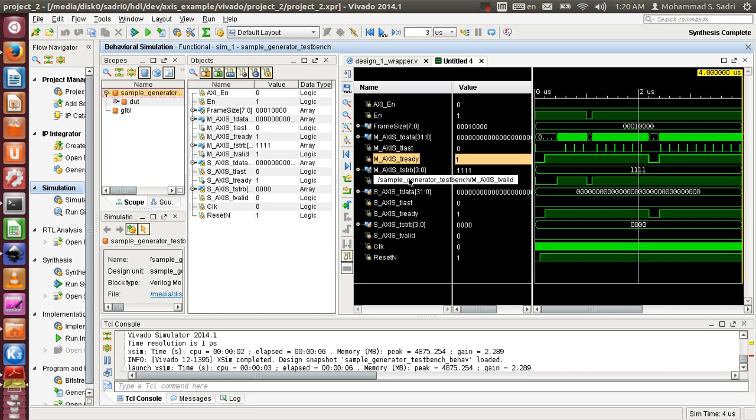And then we look at T-valid, and actually T-valid is also behaving fine, because as you remember, the only one responsible for bringing down the T-valid was the enable signal. And as you see, the T-valid goes down only when enable is not active, and in the rest of the situations the T-valid is active.